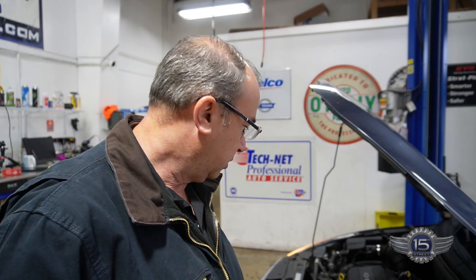I wish I could give you better information as to why that purge valve went bad, but don't forget, if you're fighting one of these lean codes and purge seems to be working, it wouldn't be a bad idea to try a purge valve. Super easy to change, and they're not very expensive. So probably should have done that a half hour ago, but anyway, this one's fixed. We're going to send it back to the customer.